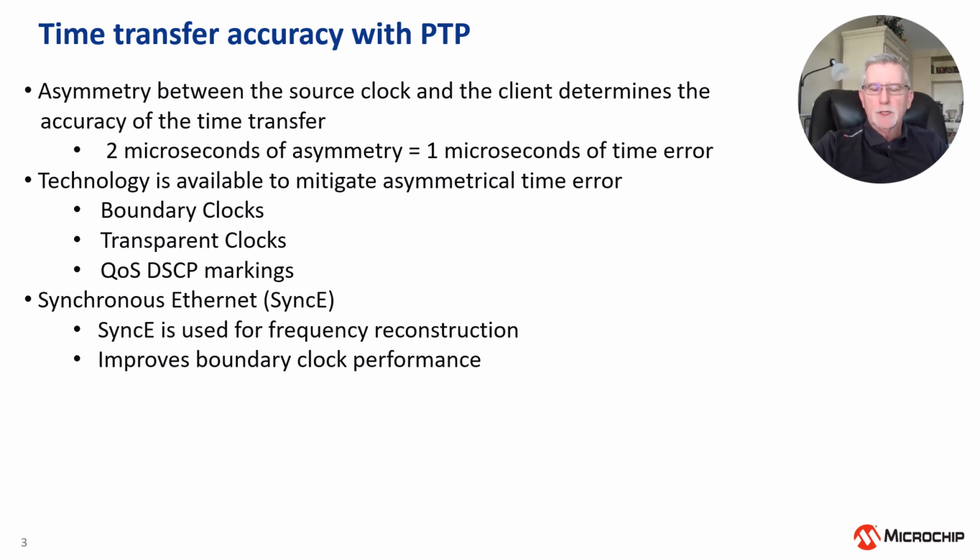So how does this work using the PTP protocol? If I send a timestamp from the receiver or the grandmaster to a PTP client at point B, when that client receives the timestamp, he's going to turn around and send it back to the grandmaster, asking the grandmaster, say, hey, what is the total delay or the round trip delay from A to B, back from B to A, and then please send me another timestamp to correct for that error.